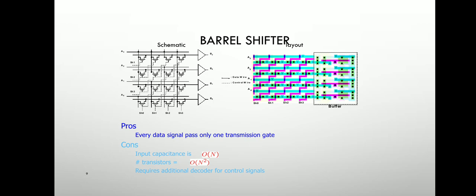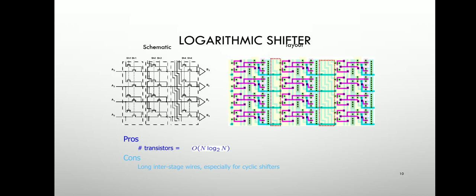The barrel shifter is used in the hardware implementation of floating point arithmetic. For floating point add or subtract operations, the significands of the two numbers must be aligned, which requires shifting the smaller number to the right, increasing its exponent until it matches the exponent of the larger number. This can be done by subtracting the exponents and using the barrel shifter to shift the smaller number to the right by the difference in one cycle.